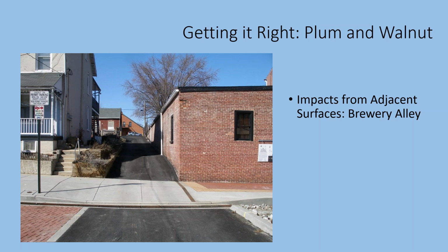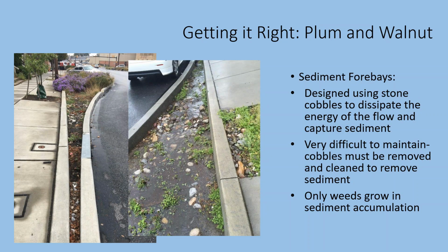So next slide, you can see some of the early or legacy influence from that unfinished alley. These systems were originally designed without sediment forebays. So when that sediment was coming down here, it had nowhere to go. It would often settle out in these small cobble channels that were designed to be low flow channels, and they became cemented in over time. So we really worked on developing a way to move around that, and the easiest way to do that we could do in-house that would also help us save on those maintenance costs would be to retrofit it with a forebay ourselves. Next slide.